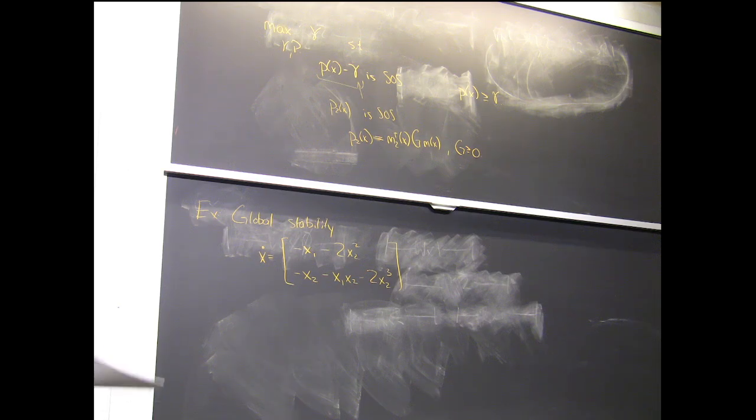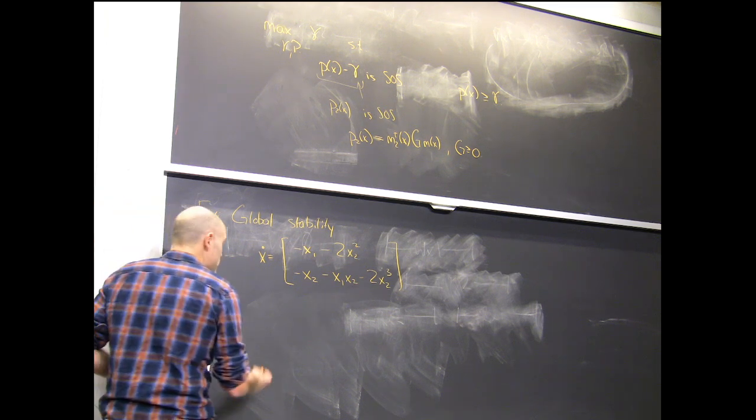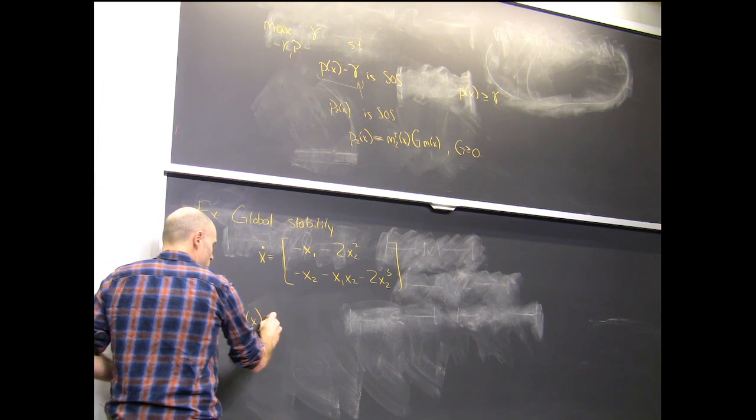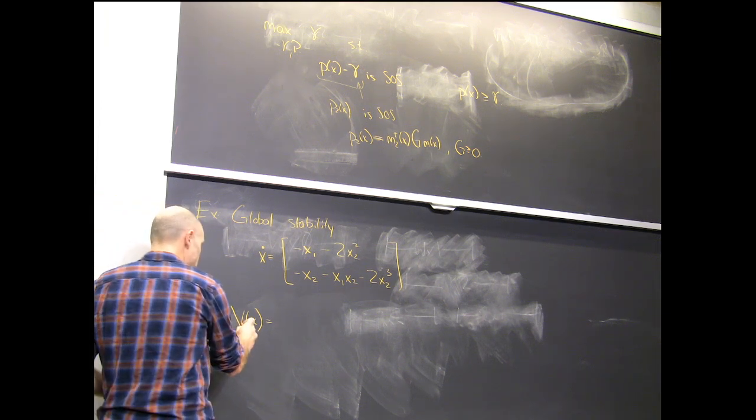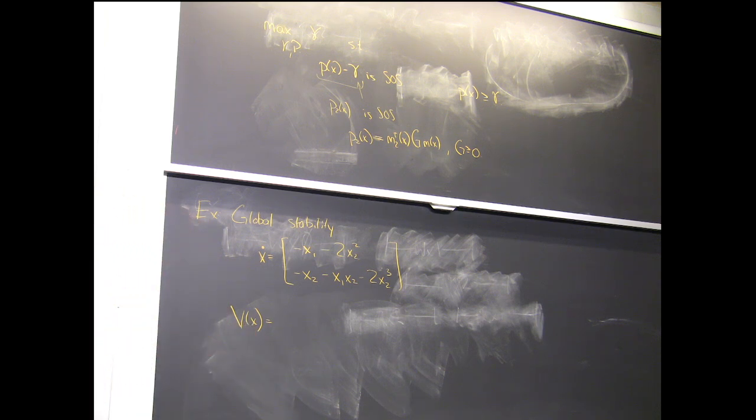And I want to use the sums of squares, convex optimization, semi-definite programming machinery to do Lyapunov analysis of this. Okay, so the first thing I can do is certify if you come to me with a Lyapunov function. If you were to come and say, I think the Lyapunov function is this function, I can do the algebra, but actually guaranteeing that it's always negative is hard, potentially. When you get a big complicated function, knowing that it's always negative requires extra machinery.